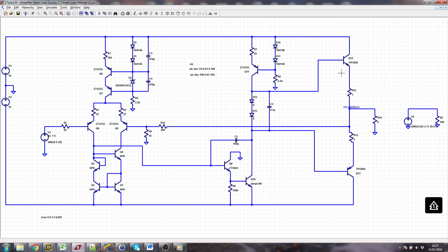Well, I say it's not a good power transistor. It's got a lot of things that I don't recommend. It's got quite a low transition frequency. It's not very good for high frequency work. It can't really dissipate a lot of power. Usually it takes quite a bit of current to drive it, because its beta's not very good. It's fairly miserable in most respects, but you could say it's got a low FT.